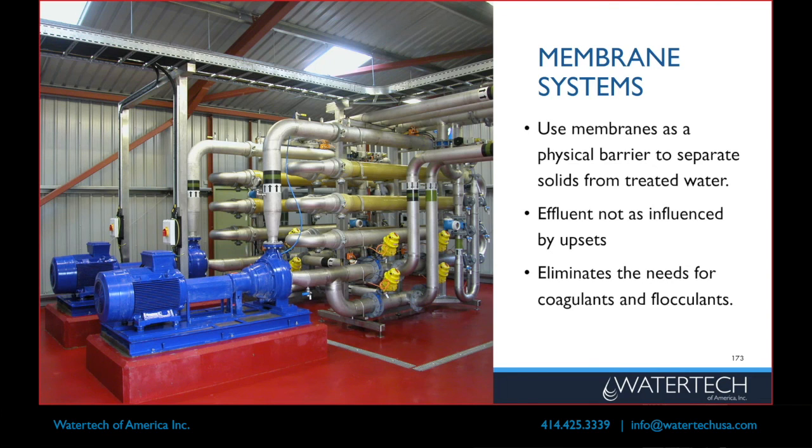You don't need coagulants or flocculants. You will need some sort of cleaning chemistry, because with any membrane system, membranes have the tendency to become fouled. So you need some acid, caustic, sometimes a sanitizer, just to clean those off and keep them performing well.